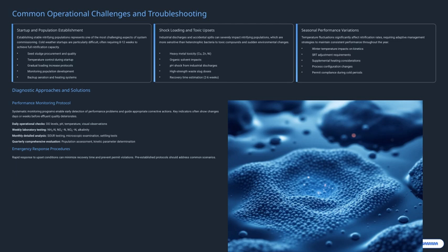Now, let's discuss diagnostic approaches and solutions. Systematic monitoring is your best friend here. Regular checks, daily, on parameters like dissolved oxygen, pH, temperature, and visual inspections, help you catch early signs of trouble. Weekly lab tests for ammonia, nitrites, nitrates, and alkalinity give deeper insights, while monthly detailed analyses, including SOUR testing and microscopic examinations, help assess population health. Quarterly, a comprehensive evaluation of the microbial community and kinetic parameters ensures your system remains optimized.